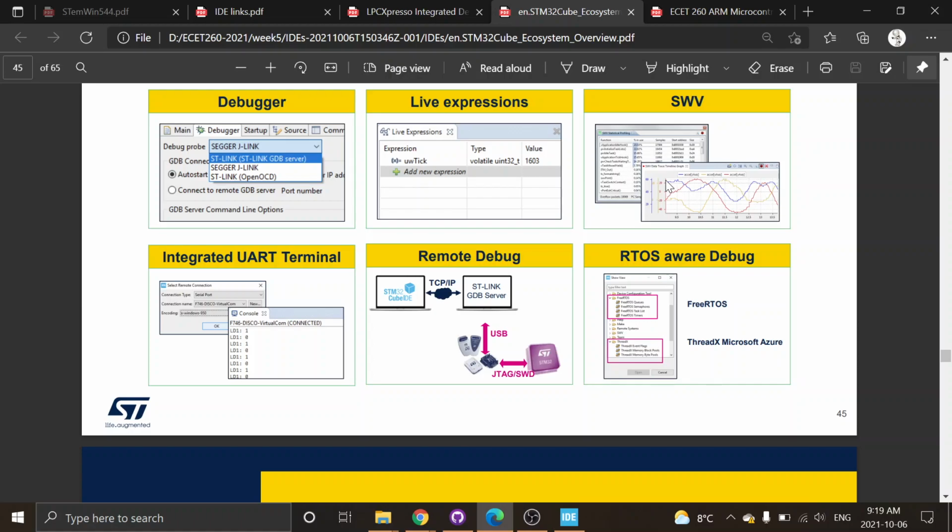I wanted you to use the monitor program because it gives you the whole Node-RED options to be able to do so much more with it. And so if you just want to have a couple of graphs and see some plots move, that's just in the drop down where we did SWV data trace, SWV console. There's also the trace viewer here that will just show you a graph. But we can also then have the STM32 monitor and open it up, get our data into something that you can do post-processing on a PC with, okay? And also show gauges and all of that.